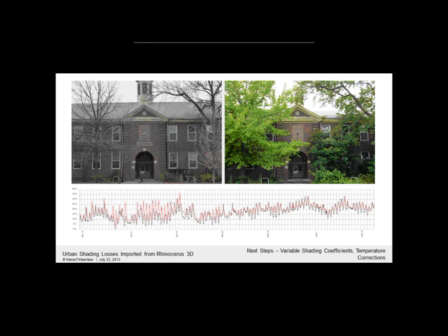So if you've been paying attention, you may have noticed something I glossed over that actually has a significant impact on the way we model shade trees, and that's seasonal variation. While our present workflow requires that transparency be specified as a constant value, we know from experience that this changes significantly as leaf density changes with the seasons.